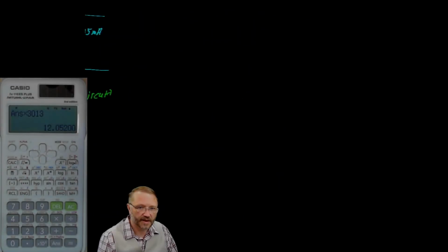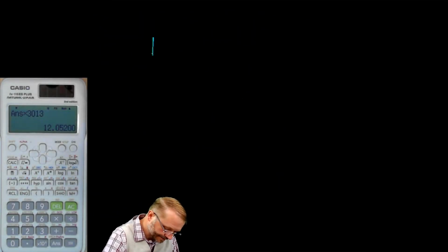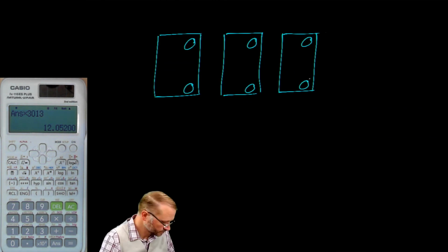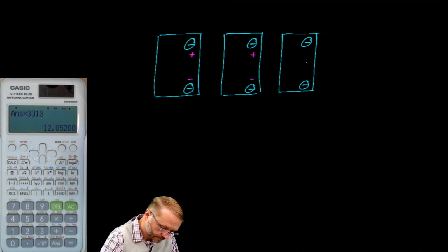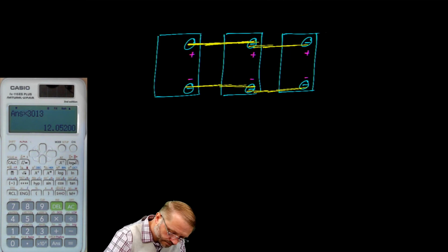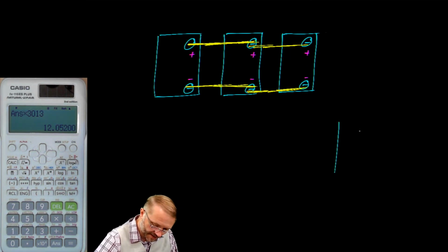Let's add a sidebar while we're talking about the batteries here. When you connect your batteries together, you're going to want to use a thick cable or copper strap to connect them together, and then heavy cables to connect to your load.